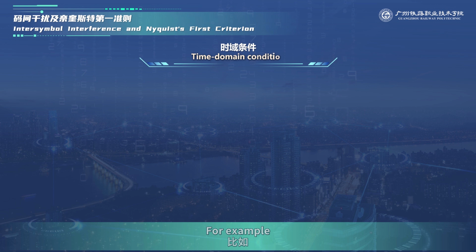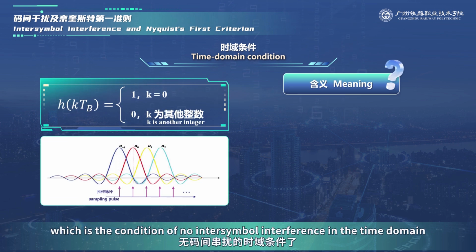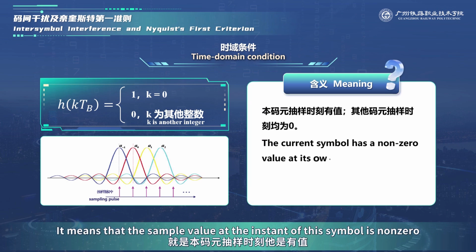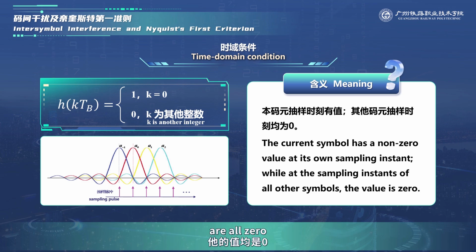For example, let's look at this graph, which is the condition of no intersymbol interference in the time domain. In this formula, what does it mean? It means that the sample value at the instant of this symbol is non-zero, while the values of other symbols at this sampling instant are all 0.